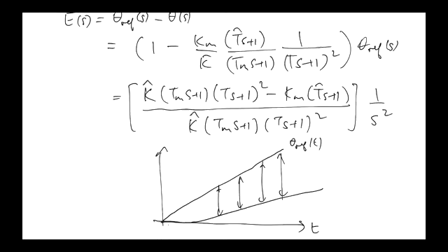All right? So that's what's wrong with open loop control. Unless you know your model exactly, the underlying inversion in open loop control doesn't work out exactly. And in this case, it doesn't even allow us to get a constant error in steady state. The error keeps on growing.